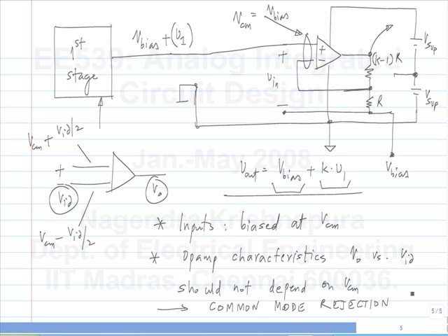Okay, but the basic idea is that the op-amp should not respond to the average value of the inputs. It should respond to only the difference value of the inputs. Okay. So, is it clear how to work with single supply op-amps? So, when you simulate and so on, this is what you do. Okay. So, everything that we do will be with a single supply. We will not use dual supplies, and this is how you can arrange your things. Okay.